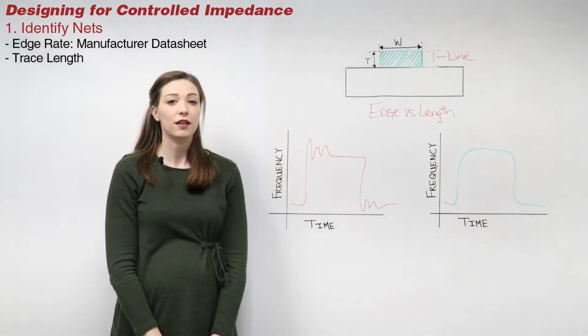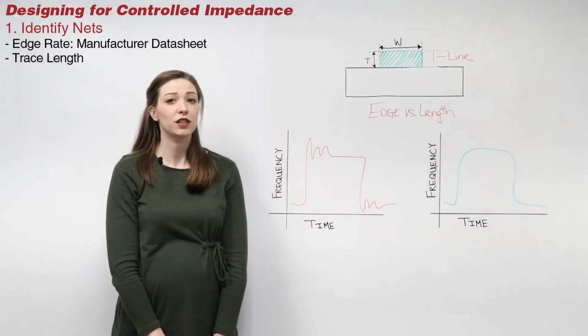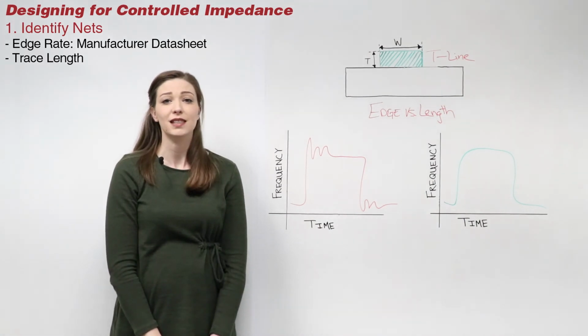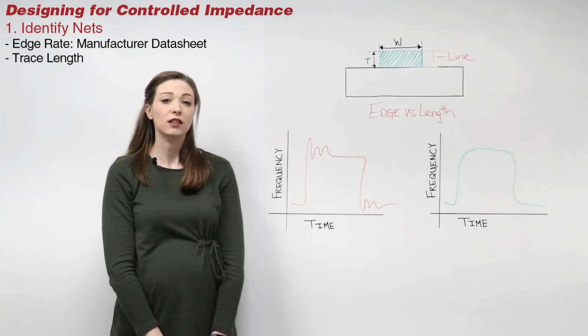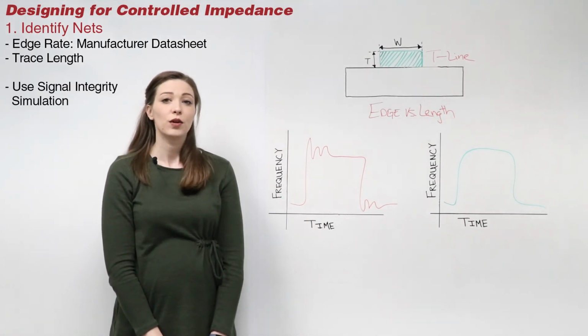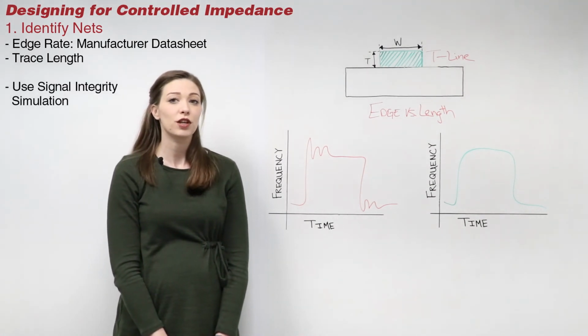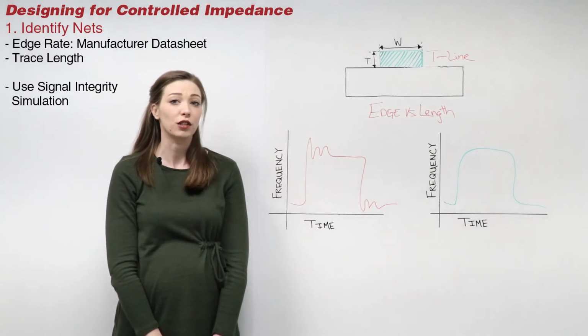Comparing the trace length and edge rate for every trace in your design can be time-consuming and tedious. Many PCB software packages perform signal integrity analysis, where you can automatically determine which traces may have ringing or reflection.